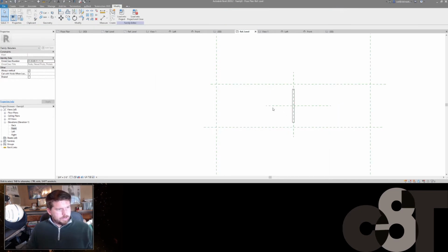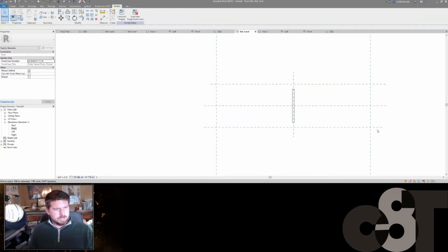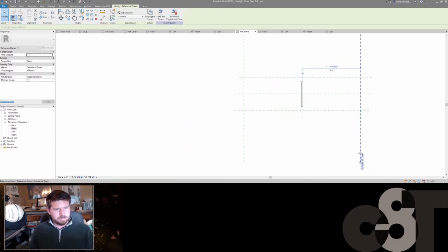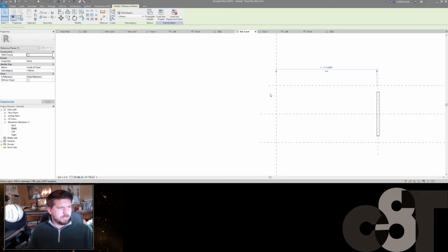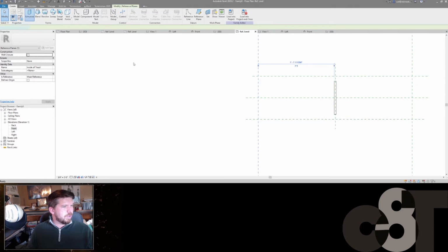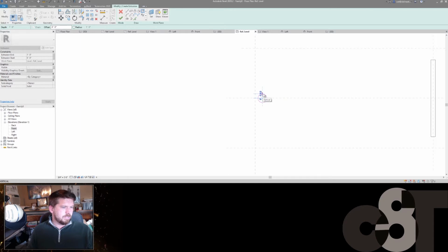We know that on one of these sides, in particular the interior side, the standoffs, the tread supports, are going to be right next to each other. All right, so which one did we make the inside? That's the outside. All right, this is the inside. Okay, so what we should probably do is create an extrusion here. This is the end of our tread, so we actually want to go inboard of that just a little bit.